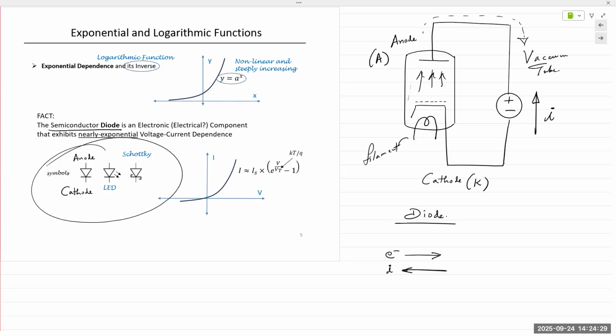There are some other specialized diodes, Zener diodes, and some other variations of the diode that come in a transparent glass-looking package. It's like plastic epoxy, but it's transparent. And it has a black or a red band. And that band, again, indicates that the terminal is the cathode. So if you look at the actual device, you will see that. LEDs, you'll have two leads coming out the same side. The longer lead is the anode, the shorter lead is the cathode.